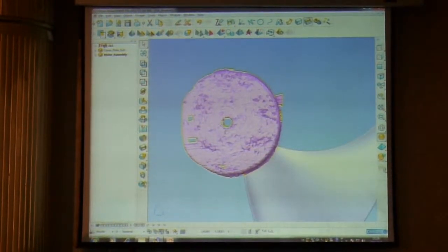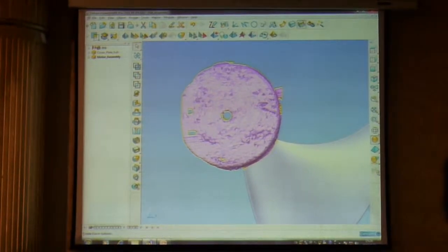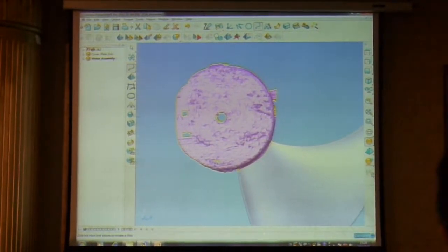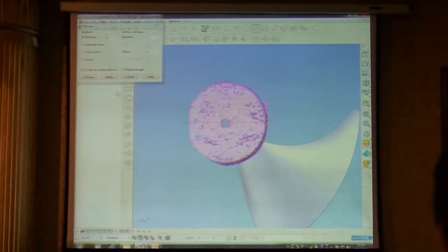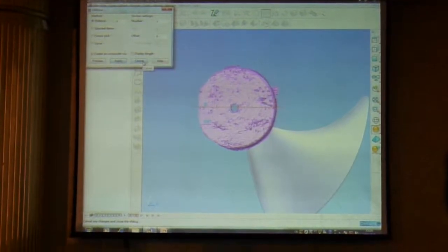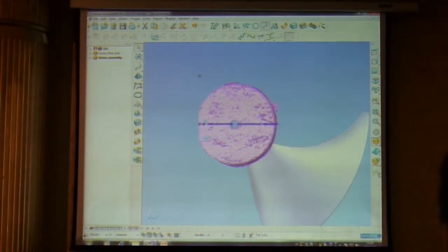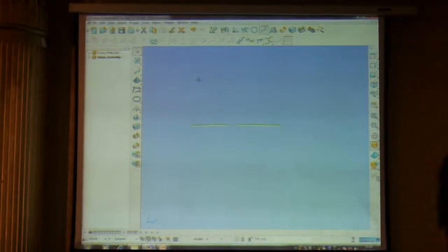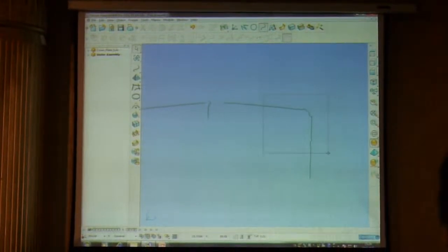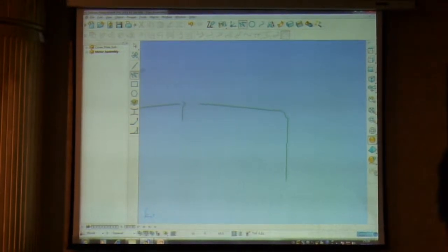So the blade is finished, so now we can turn our attention to the hub. Again, I'll start by capturing a profile through the centre of the hub, and I can do this by taking an oblique curve through the triangle data. Now, if I draw that oblique curve on its own, you'll see again, because we haven't done any smoothing operations on the triangle data, the quality of the curve that I get is far from perfect.